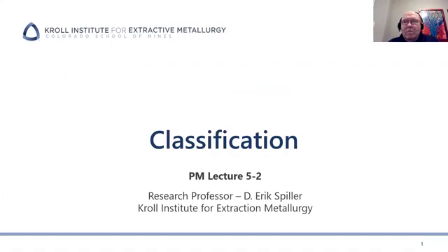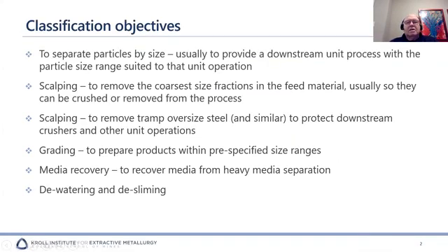You've heard the term. We talked about classification in the lectures on crushing and grinding and liberation. Well, classification is separating particles based on their size, and it's usually done to provide material that is prepared for the unit operations that follow the classification. So the big umbrella word is classification, and then there's a number of ways to do it.